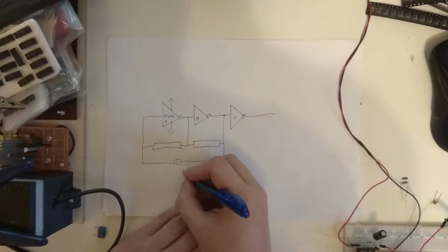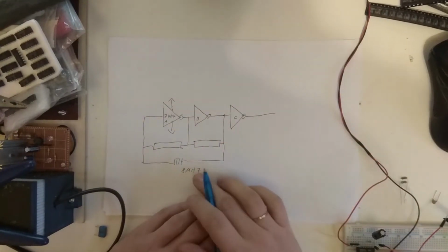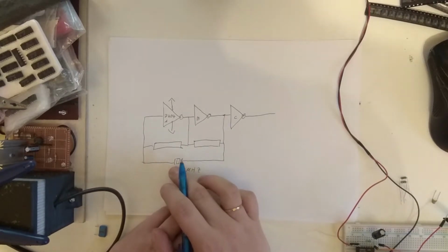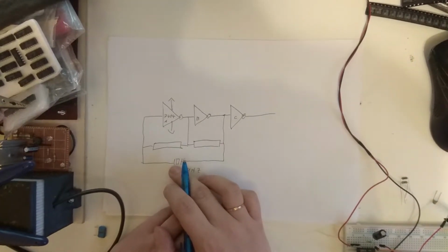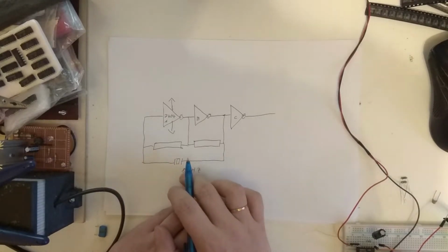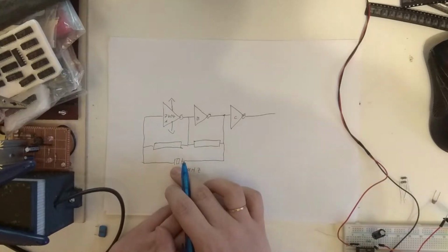In my case, I have an 8 megahertz crystal in here, although on the actual card I will put a little socket on there, a very tiny socket, so it doesn't interfere much with the crystal, because capacitance can be a problem in circuits like that.